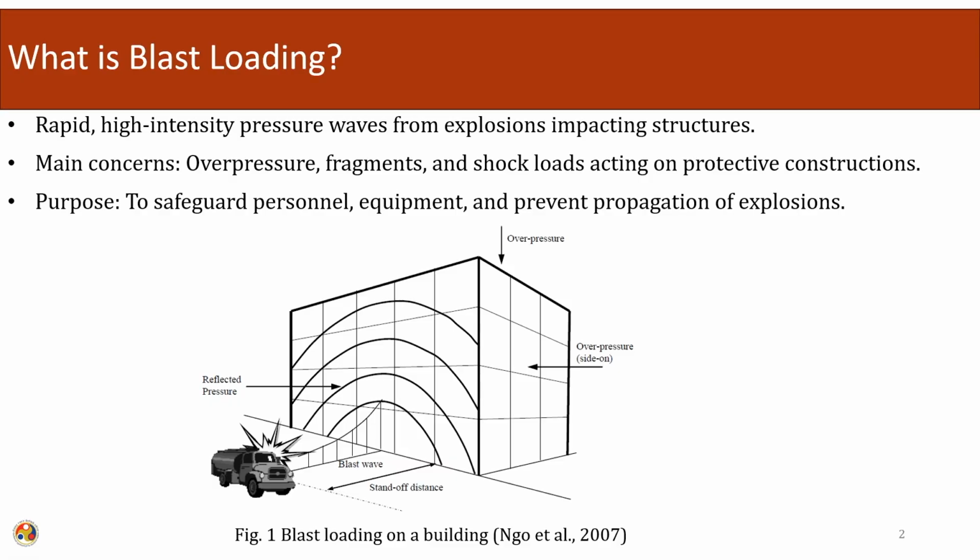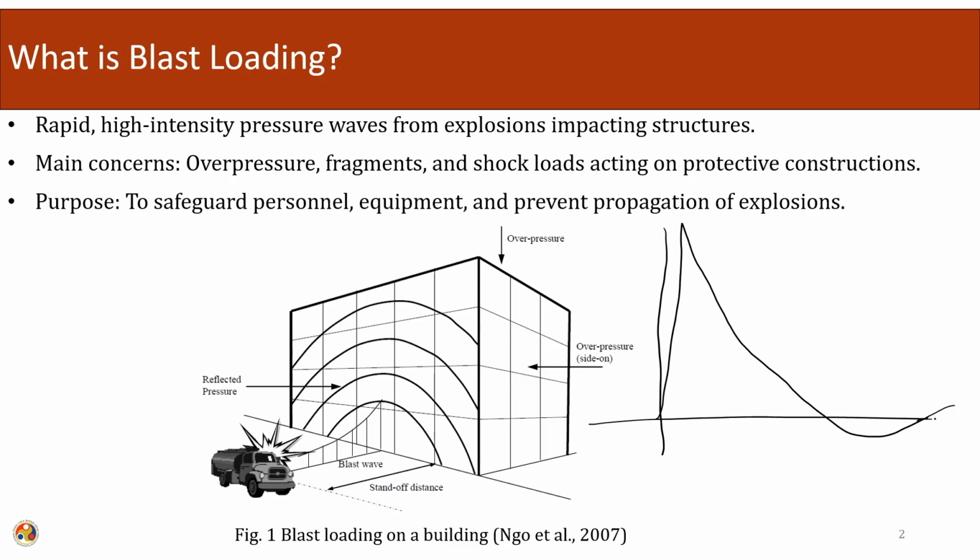Blast loading, as we have seen earlier in the previous lectures, is a rapid high intensity pressure wave formation from explosion which impacts the structure. If we look closely into the blast loading, and if we categorize it as a pressure loading, then we will see that it follows this kind of signature. So this is pressure and this is time t. It has a very steep rise. This steep rise time normally is in nanoseconds.